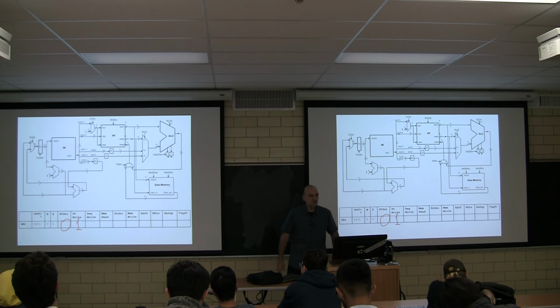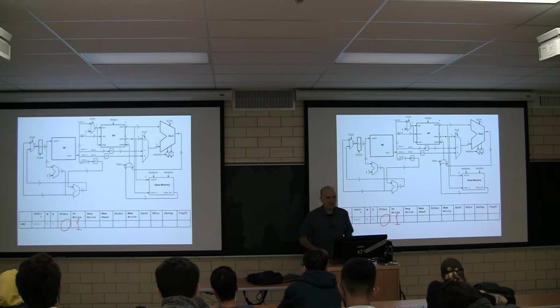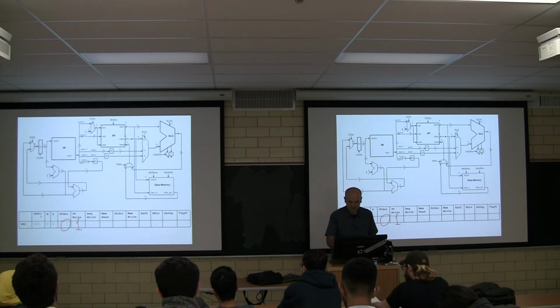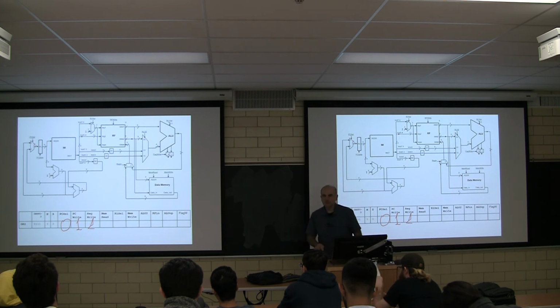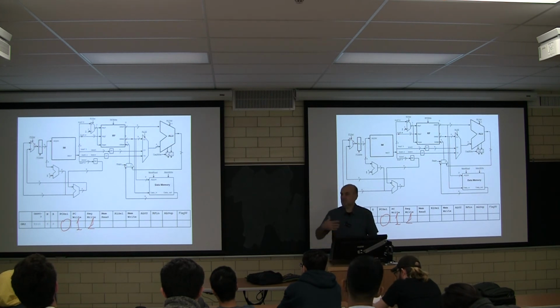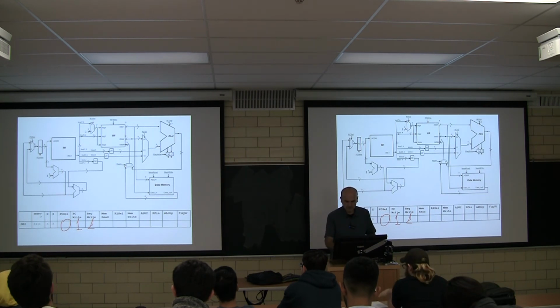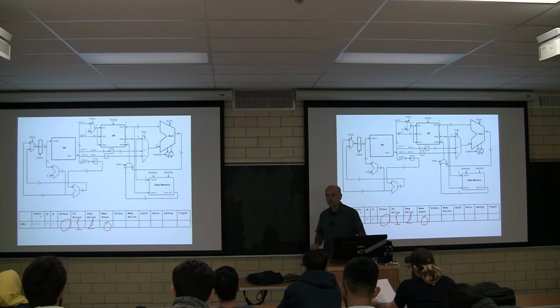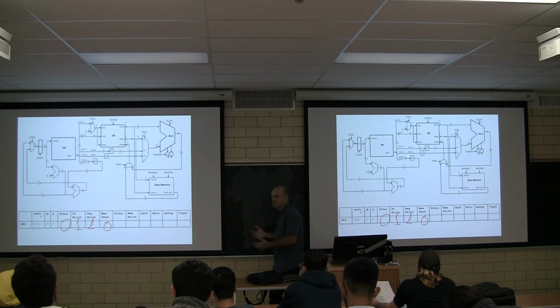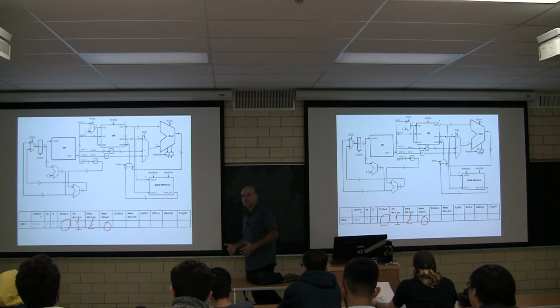Okay. Now, do we write to the register file? Of course we write to the register file because this is an OR-I. We do. Now, do we read from memory? No. Can we? Of course you could. So you could put X. However, let's pretend that memory is expensive. For that reason, I'm going to make that 0. I'm not going to read from memory. What should be the value you're going to write to the register file?